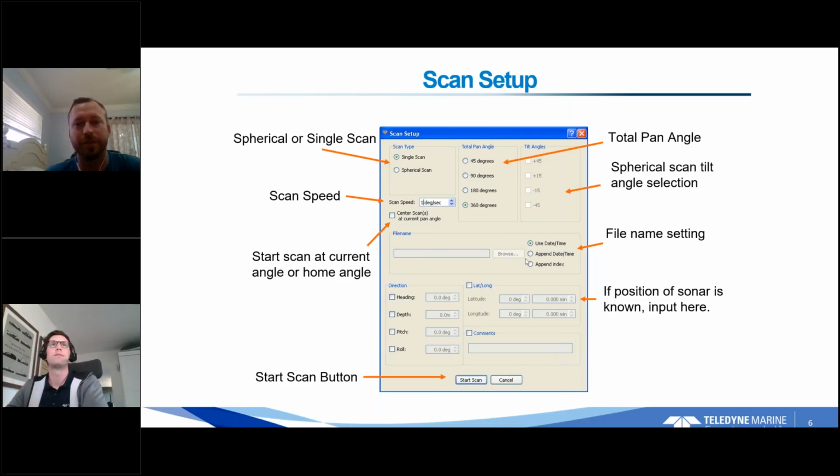So if you're just doing 1 or 2 scans, it's not as important, but when you get a big structure, when there's 10, 15 scans, it really comes into play and helps you keep it organized when you're doing the registration together. So very important to keep organized, especially if you have a big structure, a lot of locations.